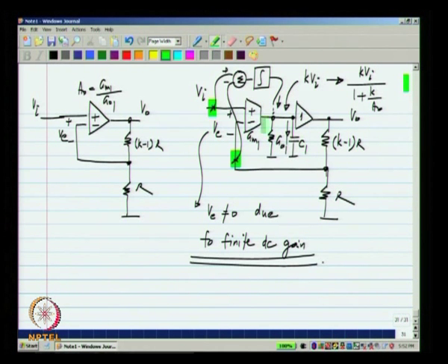okay, that is the idea. So, in other words, just to summarize again, this feedback loop settles with a steady state error between these 2 points, okay, when we use this kind of an op amp. So, what we will do is, we measure the error between these 2 points after it is settled, let us say, and then we integrate that error further and inject a current into this output conductance. So, once the current through the output conductance increases, this voltage goes up, this also goes up and the error will become smaller. It can even become 0 if this integrator is ideal, right. It is very clear, if this goes on integrating when the input is non-zero, the only way to reach steady state is when these two inputs are equal to each other or the input to the integrator is 0.